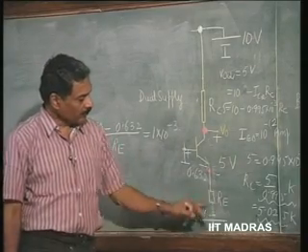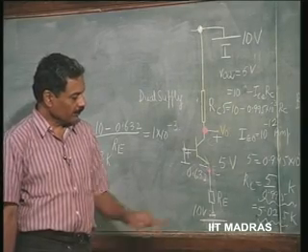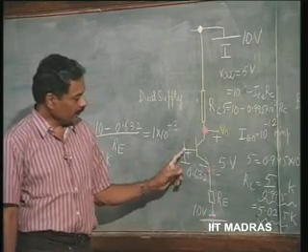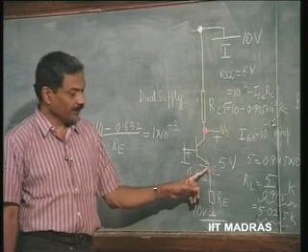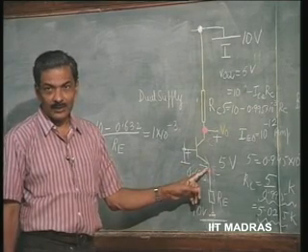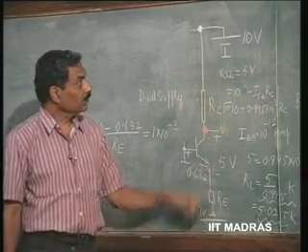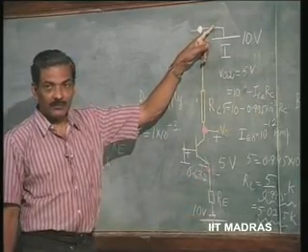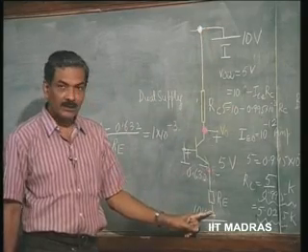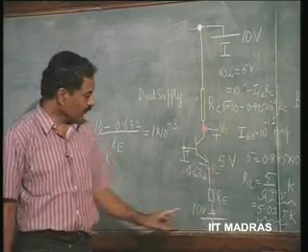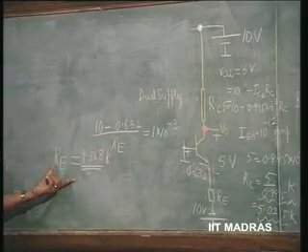So, now Re, if we introduce with another supply voltage, this base is grounded. Now, you have to apply minus 0.632 here. That is also not a good way of biasing. Instead, I will use minus 10 volts, whereas I have used plus 10 volts for the positive, a dual supply, and then put a series resistance of Re in the emitter to fix the emitter current as 1 milliampere, which is a very stable way of biasing.